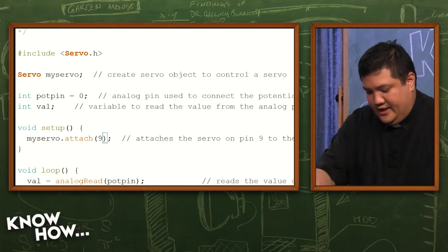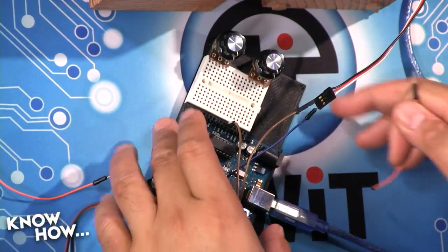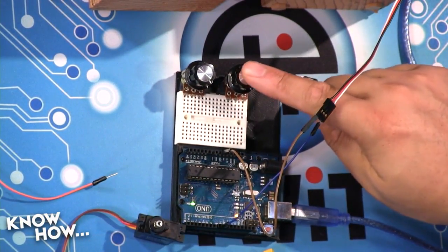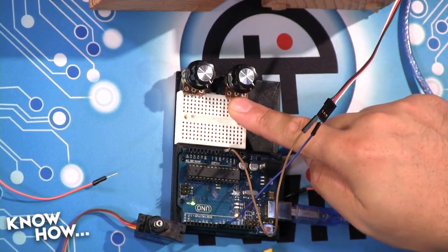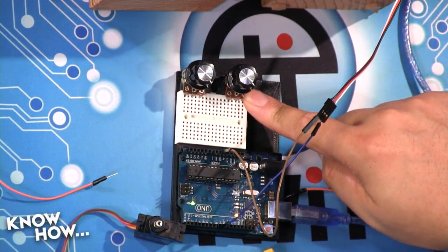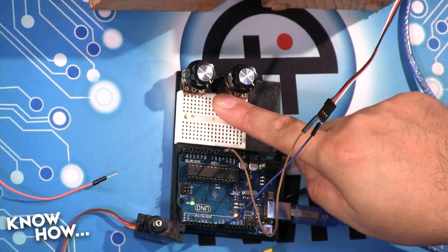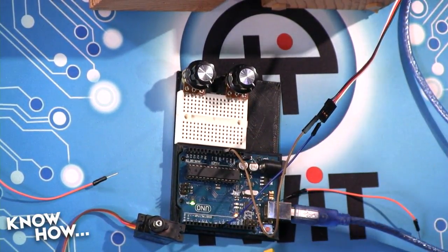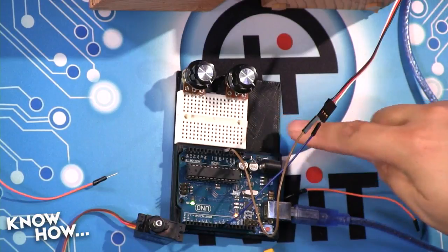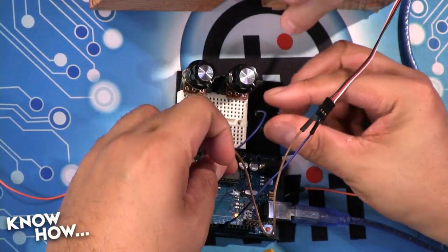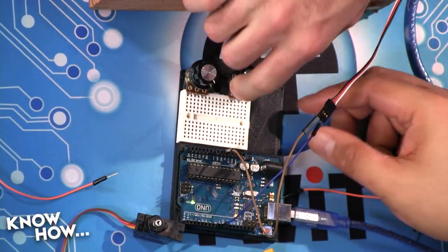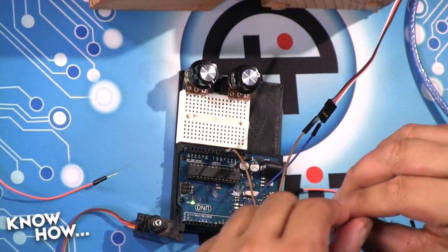Here's how it's going to look. If you go to the overhead, I'm going to use this potentiometer right here. I need to give this power. So there's 3 pins, 3 positions. I need one side to be ground. I need one side to be voltage. The middle pin is the one that's going to vary. So that's the one I have to tie into 0. That's basically your data pin? That's my data pin, right. And do you have to make sure this is at 0? Or no, it doesn't matter. Okay. Yeah, we'll reset that later on.